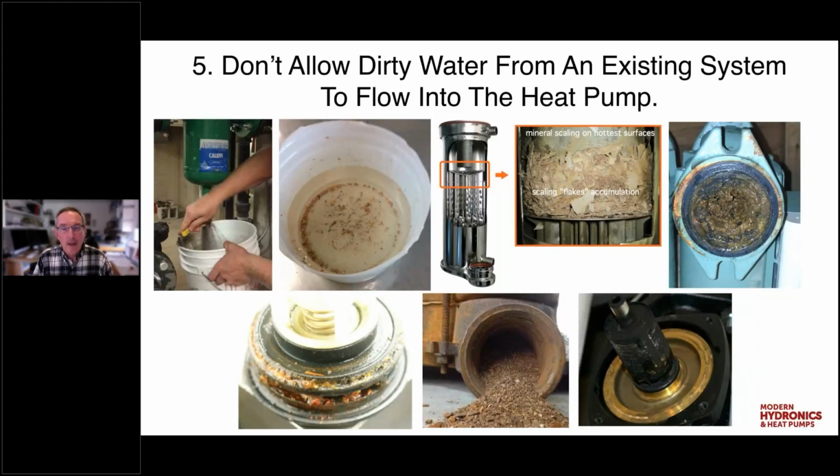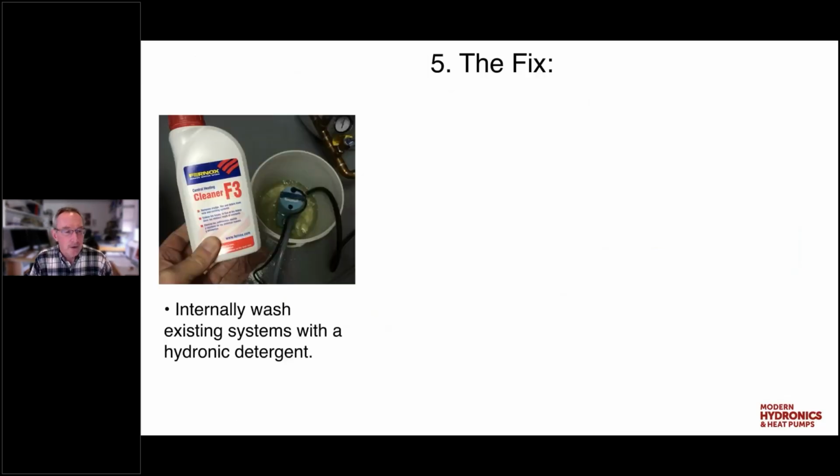So again, it's a hydronic detail. It's not really specific to heat pumps, but it's an important consideration if you're designing a new system and if there's any ferrous metal in it, but it's especially important if you're retrofitting. So there are hydronic detergents on the market. Fernox makes a product called F3. There are some other products on the market. These are basically designed to internally clean the piping.